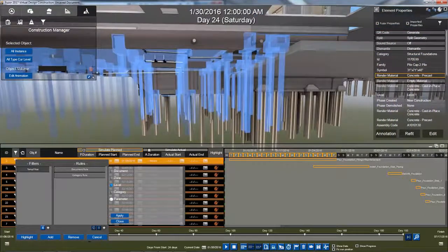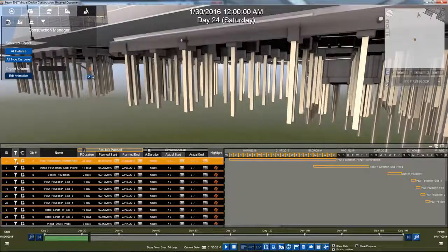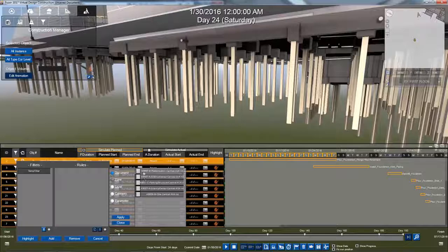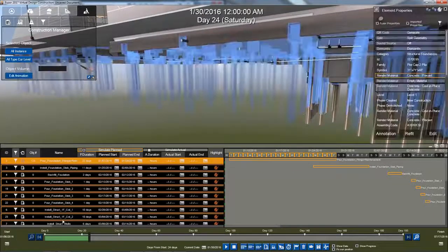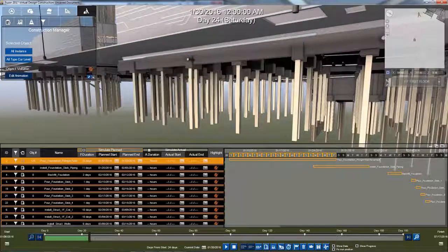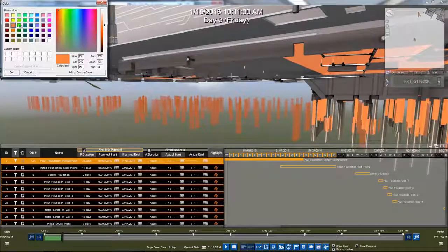To show you what that looks like from point A to point B: okay, I've got my schedule loaded. I'm going to click on that, go ahead and say only look at structural foundations, and I'm just going to hit add. So in about 15 to 20 seconds, I've got 128 objects added directly, no in-between steps, directly from my model into the task. And at the moment, they're already preset to animate in.